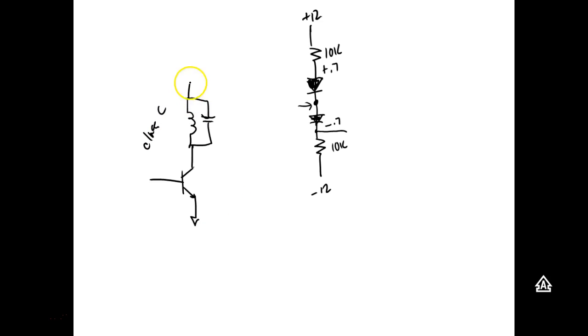And then if we take our output right here, what happens is we turn this thing on real hard, and this guy right here called a tank circuit would actually generate this right here, which is pretty neat. We're not going to explain it, but this only works at a certain frequency. So class C amplifiers, guys, are over 90% efficient.